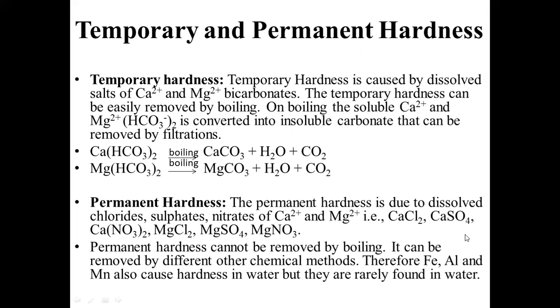We have to understand what is meant by temporary hardness and what is meant by permanent hardness. Temporary hardness, as I told you, is caused by bicarbonates of calcium and magnesium salts. And how is temporary hardness removed? It is removed by boiling. So these are the equations.